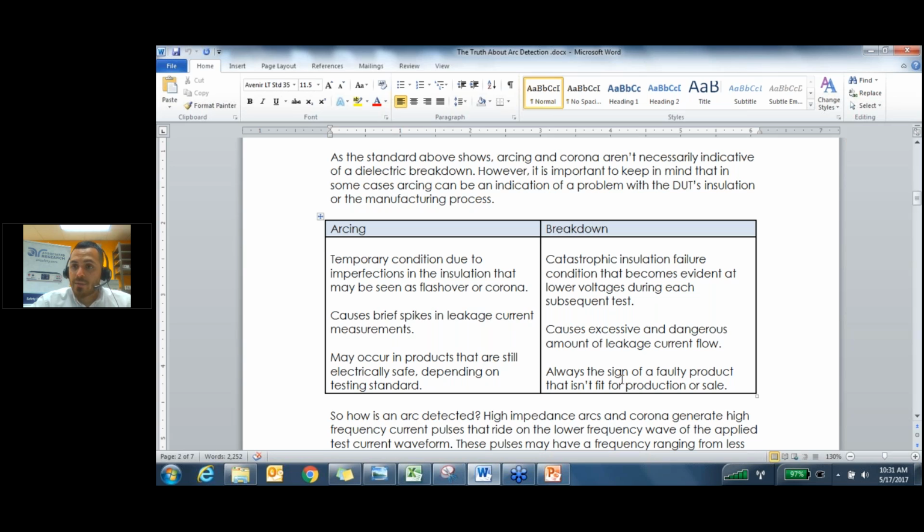And so with these levels, you can identify the exact type of current you're seeing during this arcing, and that can help you make the decision, okay, is this arcing a bit too dangerous? Is it a bit too much for comfort? Do we need to redesign, or is it only a couple milliamps here and there? If I'm failing at 9, am I failing at 8? Oh, I'm not failing at 8. I'm only failing at 9, the most sensitive level. So I'm fine with it.